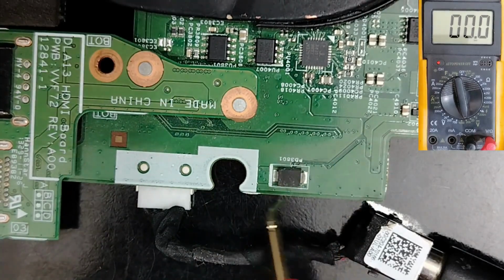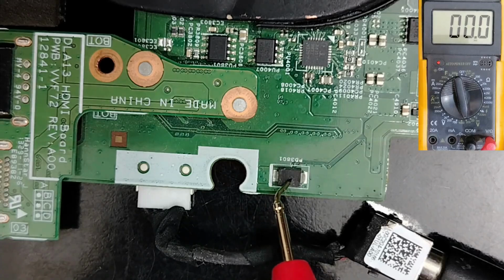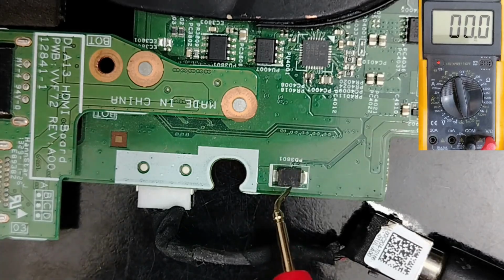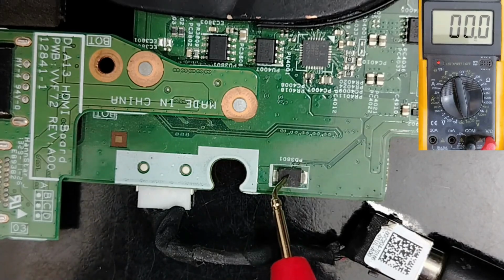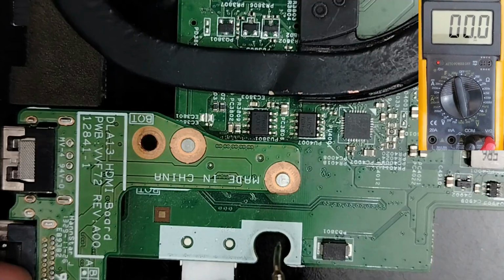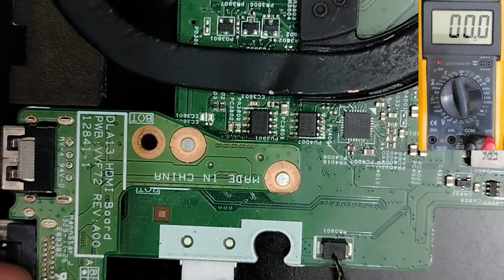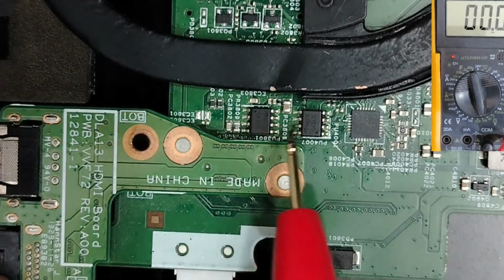Of course, sometimes, guys, you can find a fuse in place of the diode. Okay, so for protection, we use diodes or fuses. So what is the next step? After checking the protection diode, we have to go and check the MOSFETs or switches.